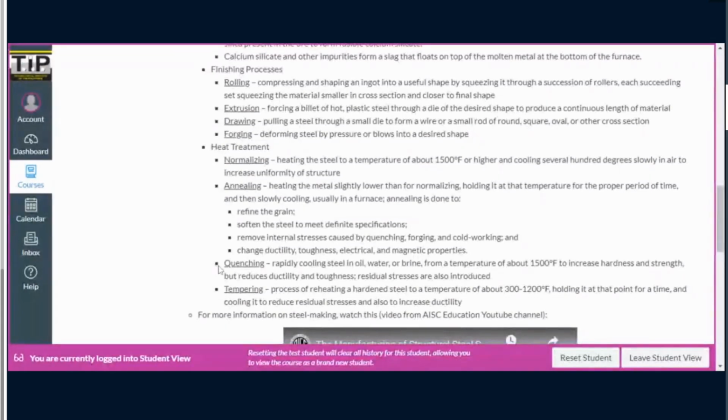Although currently there's an issue about the rebar manufacturing process, no? Because in the NSCP code, it is assumed that rebars are manufactured without these processes. However, some of the steel plants here in the Philippines already use this because it is what is practiced in the other countries. So right now, there is only a stopgap solution from ASEP, which is if you have quench tempered rebars, you may use them. However, it is the responsibility of the engineer if something happens.